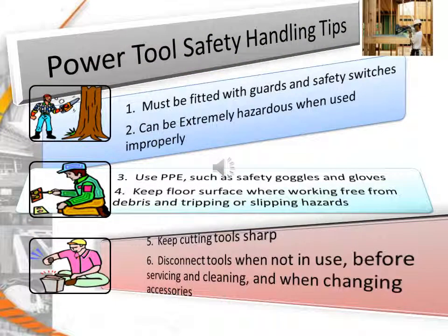Safety handling tips include fitting tools with guards and safety switches. They can be extremely hazardous when used improperly. Use safety goggles and gloves, keep the floor surface where workers are free from debris and tripping and slipping hazards, keep your cutting tools sharp, and disconnect your tools when not in use, before servicing and cleaning, and when changing accessories.